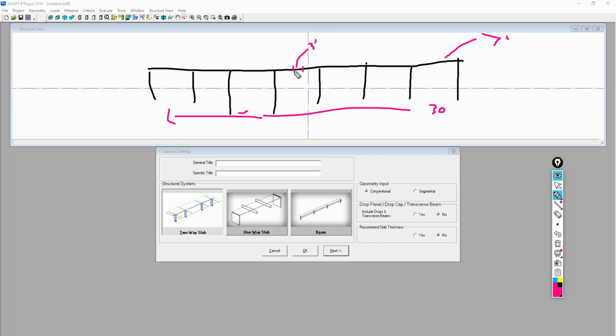And we're just arbitrarily placing it kind of at the center of span. That may not be the actual place that it's positioned. It might be shifted towards a column or maybe a moment inflection point, but for this example, we're going to put it right in the center of span. And another assumption we're going to make is that this pour strip is shored until it's poured back. So after we stress both sides, and we're going to use blue here, we're going to say there's a tendon anchored here at the face of that pour strip. It's stressed, and then on this side this tendon is stressed.